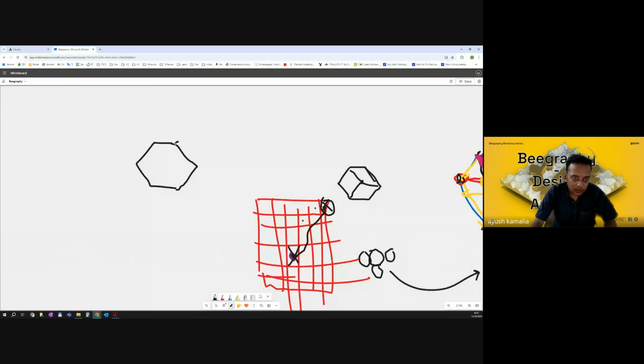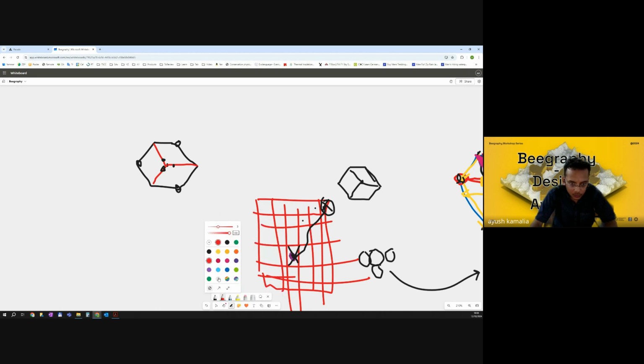we got these 3 points which were located directly on the boundary of the hexagon, checked. Second, we got these 3 lines, and then we got 3 parametrically controlled points on this line. 1, 2, 3 checked. What is the next step? Let me draw it in a blue color. We need to create a polyline connecting all of these 6 points.